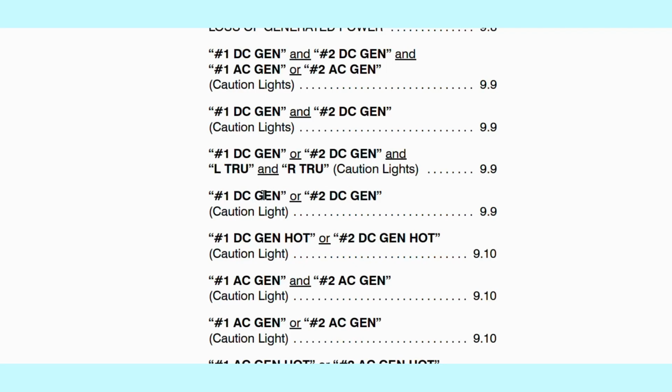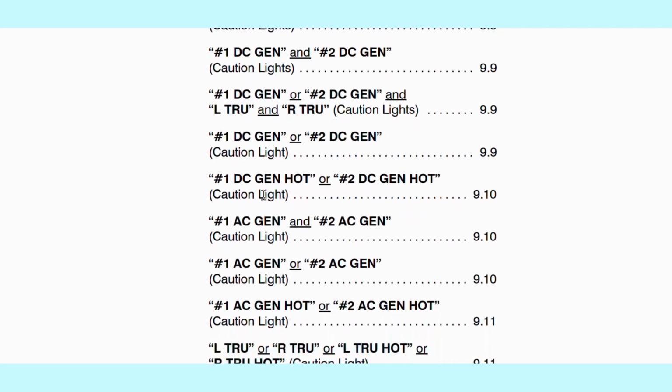I'll still continue to take off, okay, and I will see what the QRH item says. Does just switching off the DC generator resolve the problem? Then I'll be okay. Again, I'll contact the maintenance department. I'll not abort on this one.